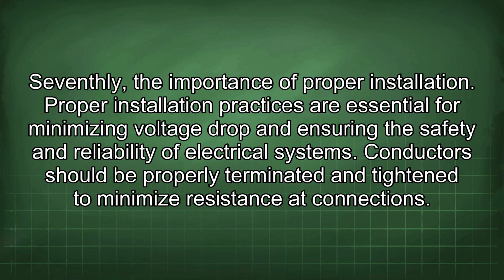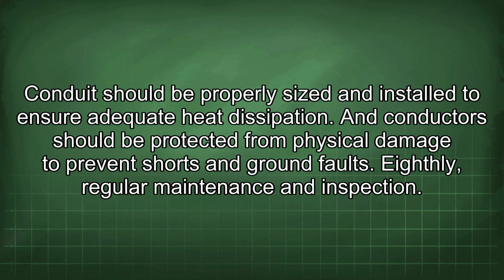Seventhly, the importance of proper installation. Proper installation practices are essential for minimizing voltage drop and ensuring the safety and reliability of electrical systems. Conductors should be properly terminated and tightened to minimize resistance at connections. Conduit should be properly sized and installed to ensure adequate heat dissipation. And conductors should be protected from physical damage to prevent shorts and ground faults.